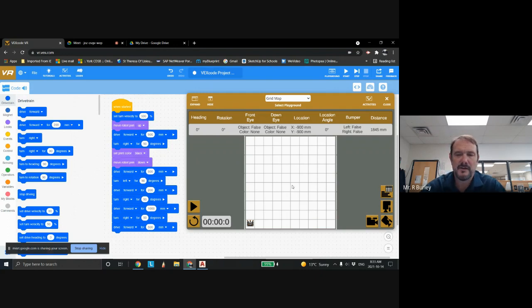So we're going to draw in this box here, but we're going to use AutoCAD to draw the CAD, to draw the object. And then we'll use AutoCAD to measure the points, the Cartesian points, to then come back into this software and program the robot. In the background, it's Python coding. We're going to be using block coding to do that. In this particular software, we can't change the block coding or the Python. You can't edit it. On our desktop stuff, we can, but in here, we can't. It doesn't matter anyways, because this is a lot of the ways that robots are programmed in the real world anyways, is they just drop in boxes and address the IO and so on.